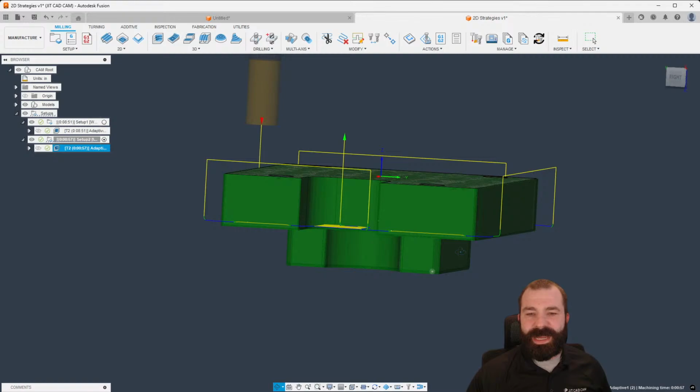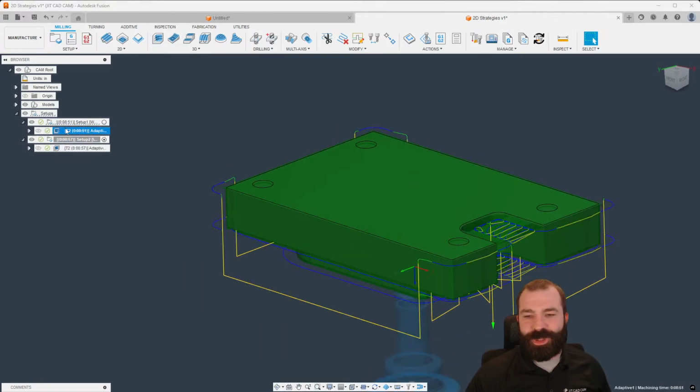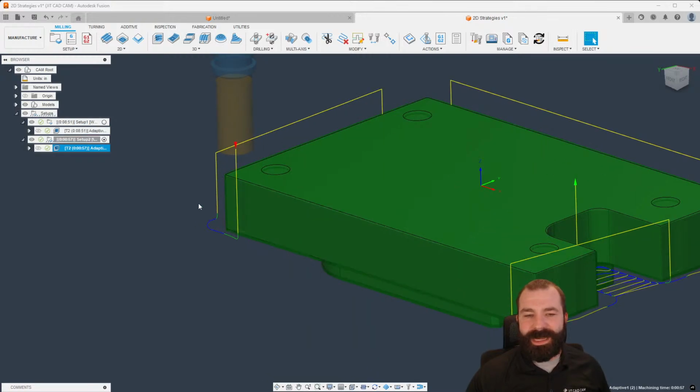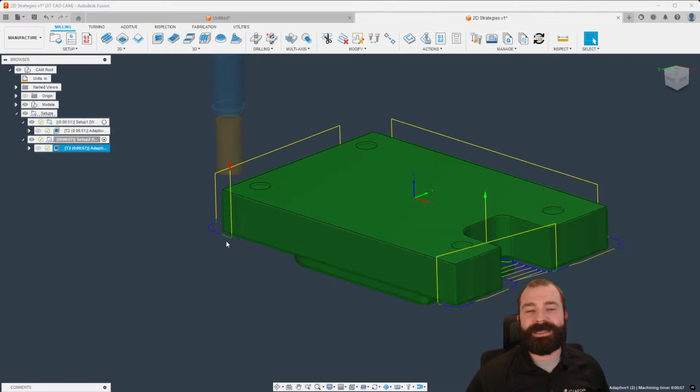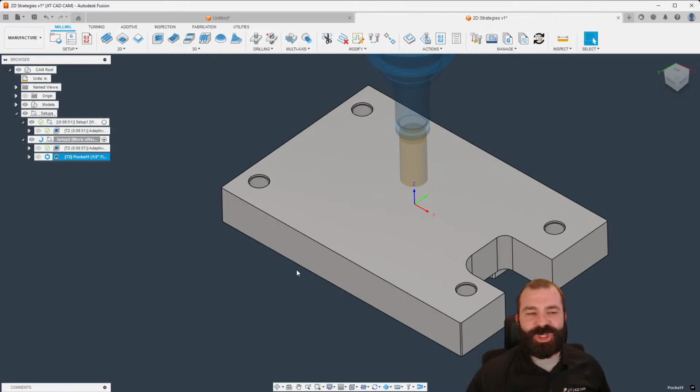So again, you guys can see, feeding back the other way, we are getting a little bit more than we should because we've already machined around that cusp the first way down. So going back the other way, we are still getting some type of additional passes that we should not have. Now, if we were to do this with 3D pocket clearing, let's shift gears here real quick.